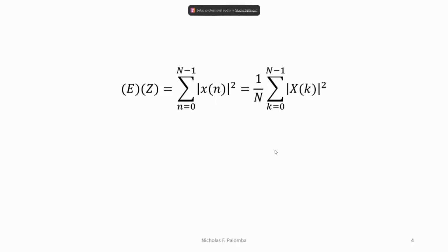So upon inspection of this equation, we can clearly reduce the energy consumed by a discrete signal by ensuring that we minimize the quantity of samples taken, ensuring the magnitude of the signal is as small as possible, and ensuring that the driven load, Z here, is as large as possible.